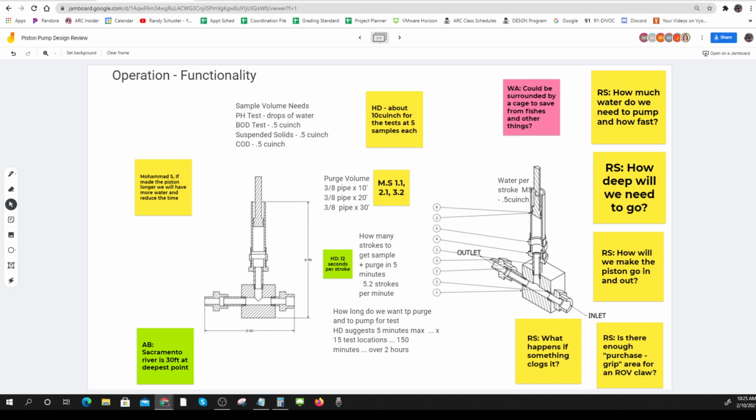So there's a few things to talk about here, right? So, what do you guys think? If you want to run a diaphragm, could be used, but how do you make the diaphragm go back and forth then? Something still has to push it. But yeah, a diaphragm could certainly be easier because then you don't have any force from the O-ring and you don't have problems with thermal expansion. But how do you push that? There's got to be some sort of a force that pushes it.